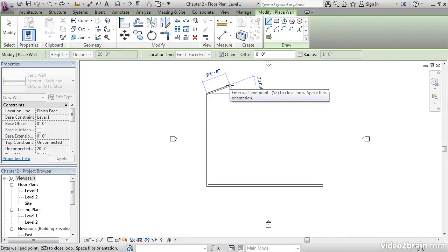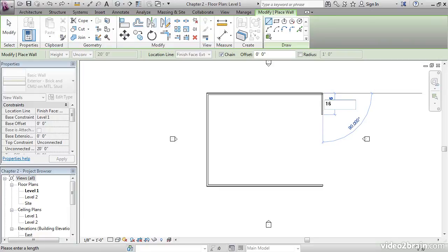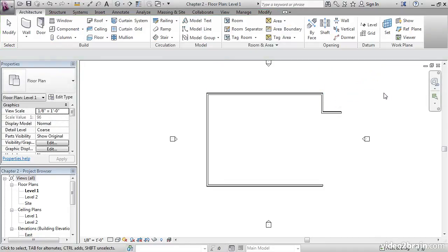This will be hard if you go back to AutoCAD. Move your crosshairs this way. Notice that there's no what's called an ortho. Revit will snap to the direction you want to go in. So if you keep coming in this direction, notice that Revit will align itself with adjacent geometry. This is a nice function. Either let Revit track the wall below it, or type in 100 feet. Bring your cursor down in this direction and type in 16 and hit enter. Move your cursor in this direction, type in 16 and hit enter. To get out of the command, press escape a couple times.